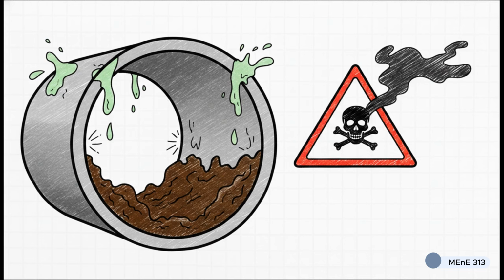Slagging happens when ash melts and coats the inside of the combustor. Chlorine combined with water vapor, that creates literal acid rain inside your pipes. You have to know these properties beforehand, no exceptions.